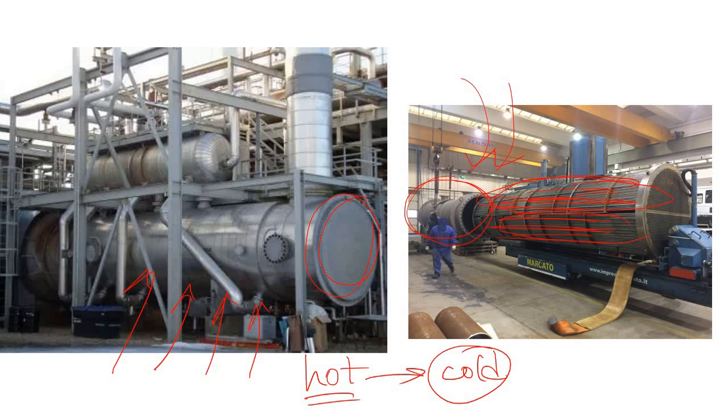Now this exchanger is normally installed on the ground because it's really heavy. Not only that, it produces lots of lateral load. How? Well, in the next slide I will discuss. Due to this huge lateral load and vertical load, normally these exchangers are installed over the ground. But in some cases, due to the piping department requirement, you need to install them over the floor, or in some cases you need to build a separate exchanger building particularly for these exchangers.